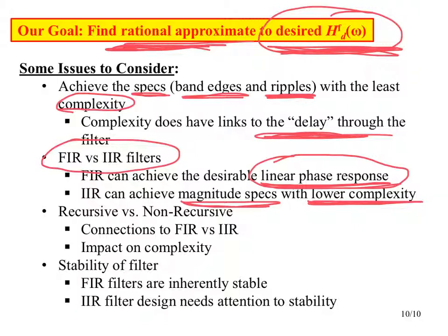And so there's been much emphasis on how to design linear phase filters, and basically those can be implemented with FIR filters, but not with IIR filters. And then from the perspective of implementing this thing, we've got recursive versus non-recursive implementations, and we've already talked about how there is a connection of that idea to FIR versus IIR, and also its impact on complexity.